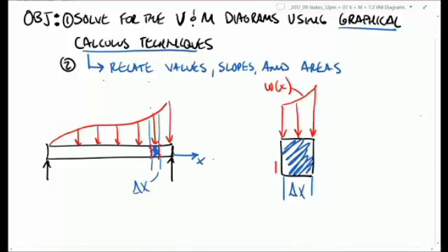I can assume positive shear going up because it's opposite the right-hand rule. Wrapping around the other side, positive shear assumed going down. Both my couple moments, M, internal, will be going up to make that beam smile.